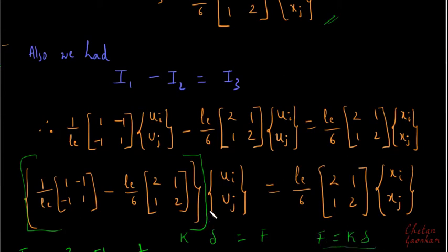So this equation will also give us the Hooke's law kind of equation, that is forcing function is equal to stiffness times the displacement, and displacement is what we need to find for the given stiffness. So this quantity is a stiffness like quantity, this is the displacement like quantity, and this is a forcing function like quantity. So that is why initially, while adjusting those integral terms, I had kept all the u terms together,